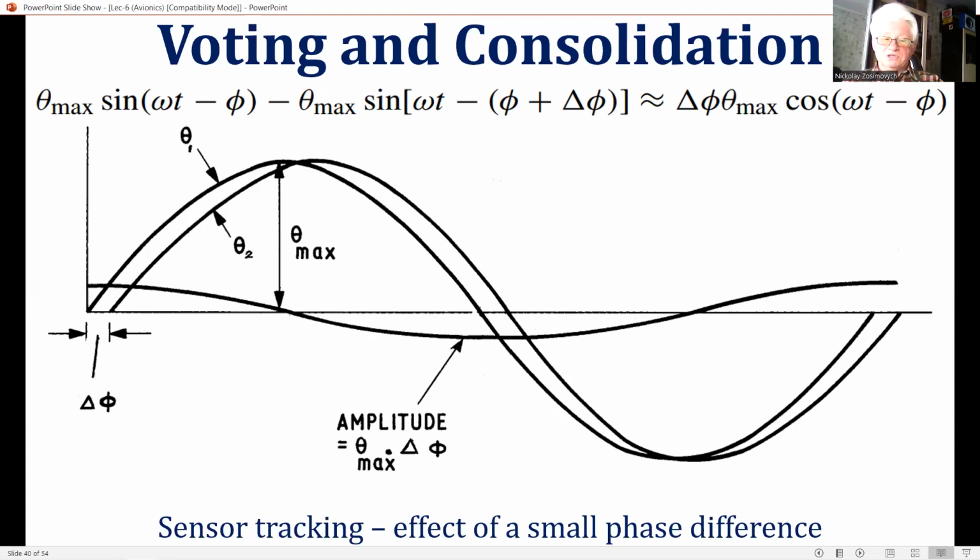The absolute accuracy of the sensor is rather less important, within reason, than the variation or tracking error spread between individual sensors, particularly under dynamic conditions. For instance, a situation where all the sensors were in error by nearly the same amount and the variations between the individual sensors were small would be preferable to a higher absolute accuracy but a larger variation. Variations in the dynamic response of the parallel sensors must be small.